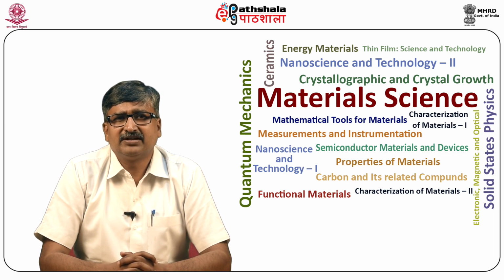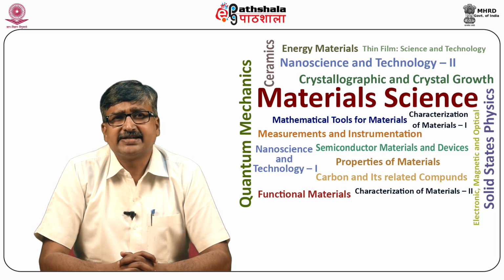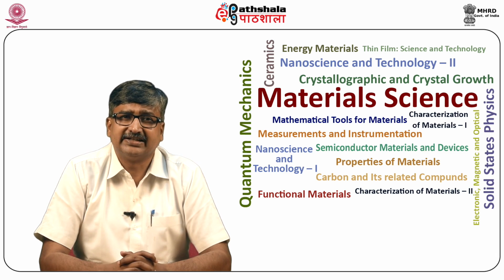TMDs with the chemical formula MX2, where X may be sulfur, selenium or tellurium, and M is the transition metal, represent a particularly interesting class of 2D materials comprising both semiconductors and metals. For example, MoS2, MoSe2, WS2, WSe2 were shown to undergo a transition from indirect to direct band gap material when their thickness is thinned down to a single layer.